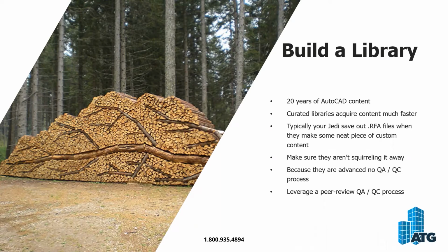They didn't create just something monolithic that's not meant to be altered later. There's even QA/QC process that goes beyond a standard of care that most firms have. You might frequently have things that when you shrink them down too much, they break, or if you move them whatsoever, they break. If you've got good families, you can make them better, and we'll detail some other ways to up your QA/QC expectations later.